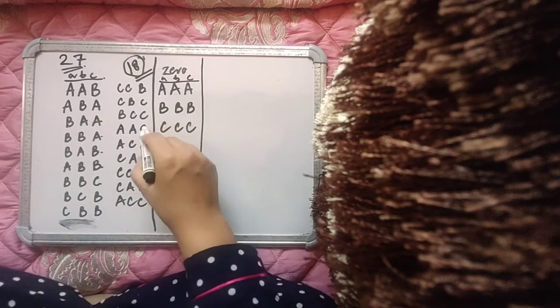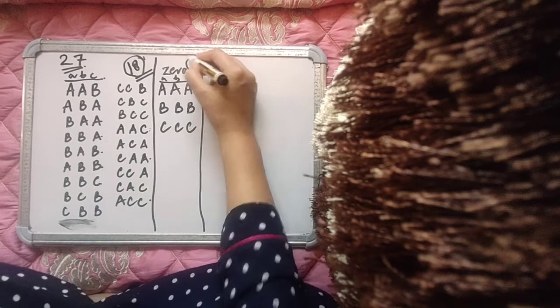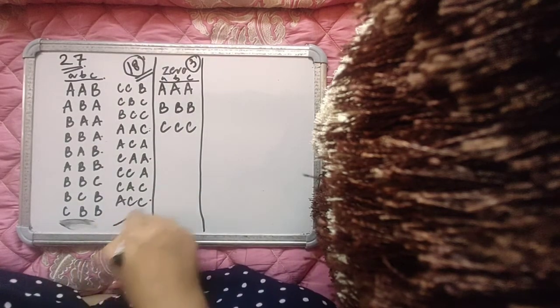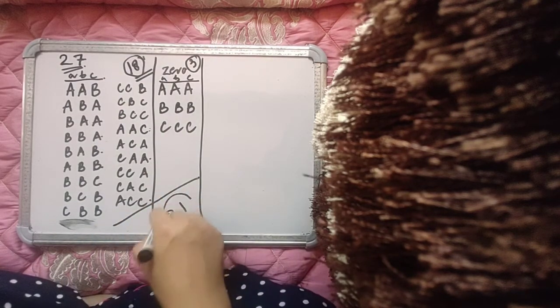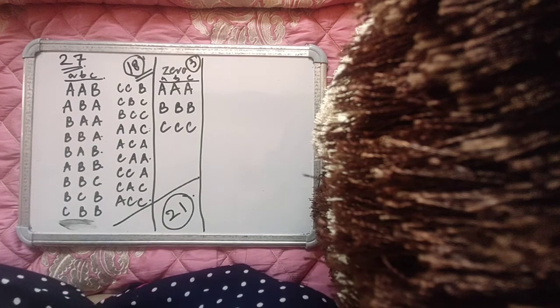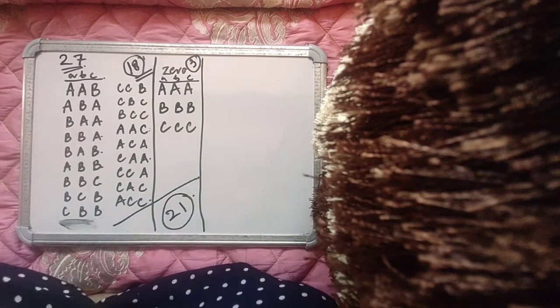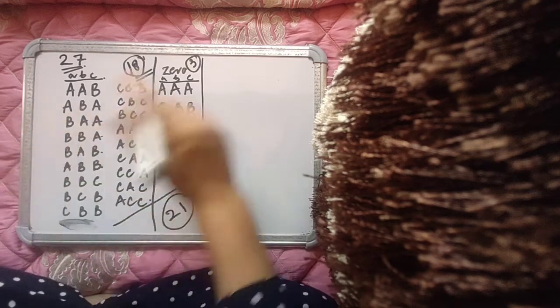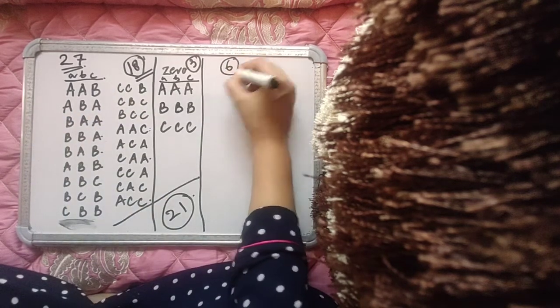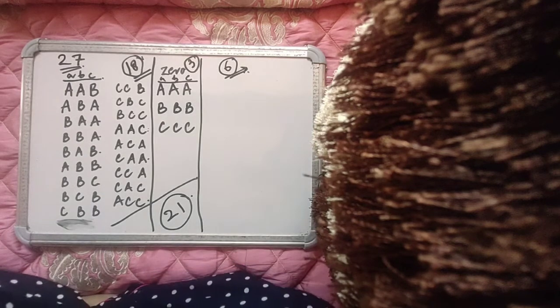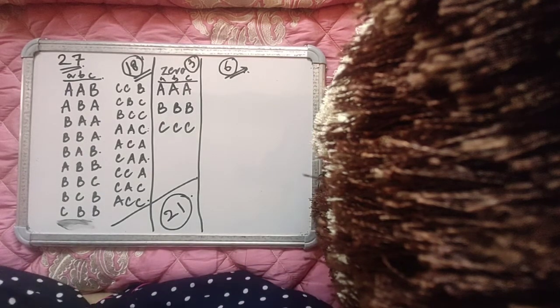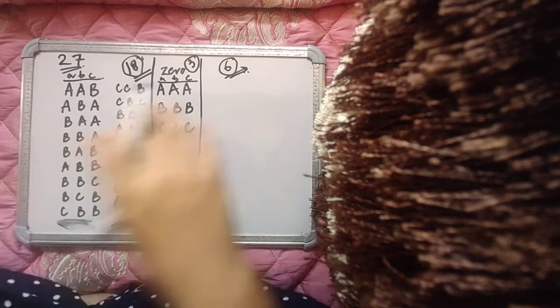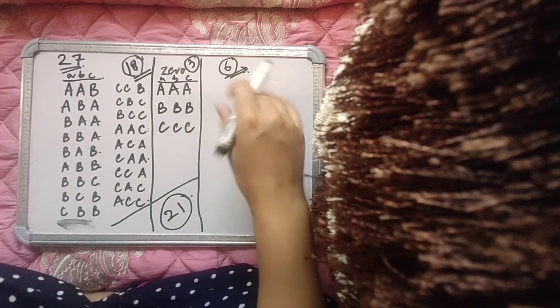Now these 18 plus these 3, that is a total of 21. Most of the time you will see that when you are implementing space vector modulation, you will use only these states, right? Apart from these 21 states, there are some more states called the 6 rotating vectors, which are also used sometimes. They have their own set of advantages, but most of the time they are not used, and I will also discuss why they are not used.